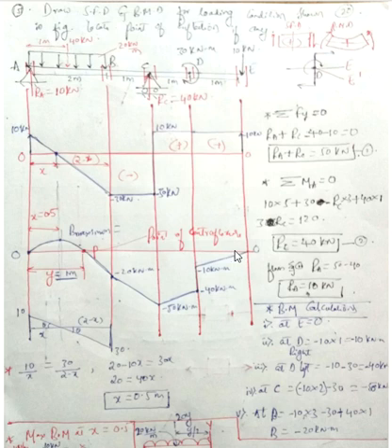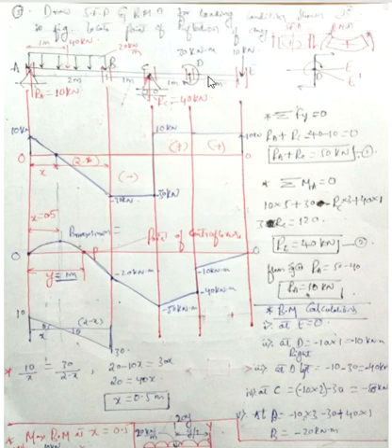First draw the horizontal line which represents 0 bending moment. Okay, now at this point bending moment is 0. Now consider this section. Whenever there is constant bending moment, always consider both the sections. Now consider first right section. For right section, come from right side, there is a force of 10 kilonewton which is bending the beam downward like this. With respect to this section, it is bending the beam downward, so we need to take it as minus 10 into distance 1, so it will become minus 10 kilonewton meter. So I am joining it with this straight line, minus 10 kilonewton meter.